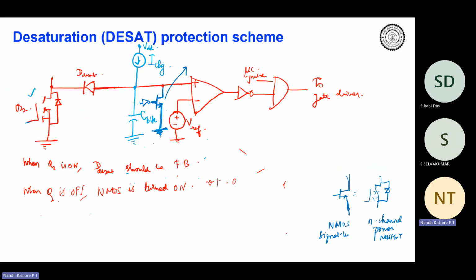So you can imagine two scenarios over here. When 400 volts, or whatever is the bus voltage, was appearing over here, if you didn't have the diode, then what would have happened? One thing is, of course, due to high voltage, the op amp would have blown off. Second thing is that there will be a false trigger that says there is a fault over here. So by making sure that you have this NMOS arrangement, you're clamping the voltage to 0 at the V plus terminal when the device is turned off. Okay. Right.